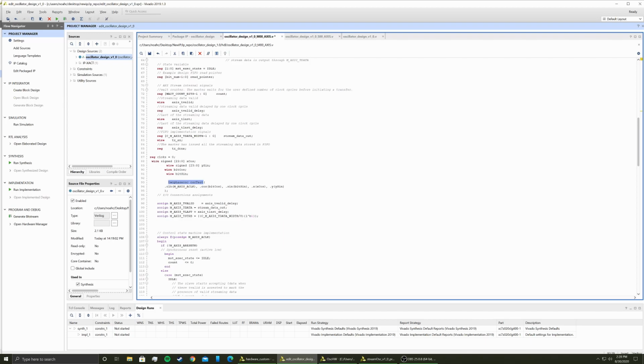But essentially, I instantiated my module, essentially running given parameters. So I implemented the wires I created. So I created a bit cosine wire, a bit sine wire, a 24-bit cosine signal, and a 24-bit sine signal that goes within my design. And I let it run at the same clock the master clock does, which essentially is just the system clock of the entire hardware circuit.